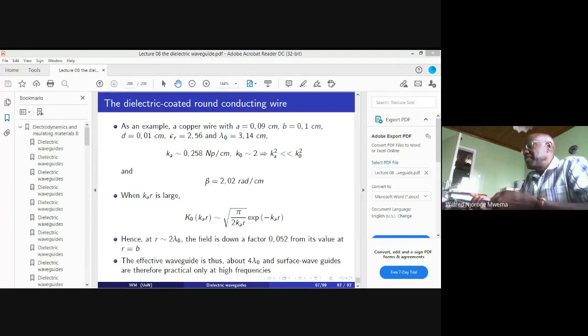Yeah, capacitive impedance should decrease with increasing frequency, because it's usually divided by the frequency. But this capacitance that we have now is increasing with increasing frequency. And that's why I called it an anomaly, because it's behaving like a capacitor, but with a capacitive impedance that is increasing with frequency.